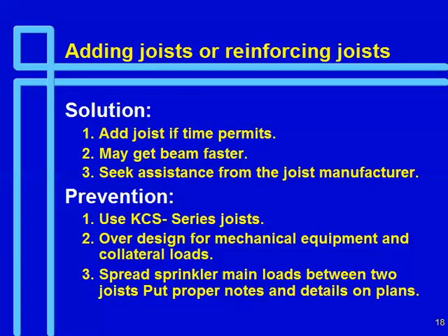Often though it's a crisis situation, and by the time you can get a joist out of the joist company to put it in place, it's too long. Maybe you can get a beam faster. So that's my next favorite thing to do, make one of those beams with the special joist seats and get that to the job site. Get it from one of the two friendly fabricators that are in the audience here.